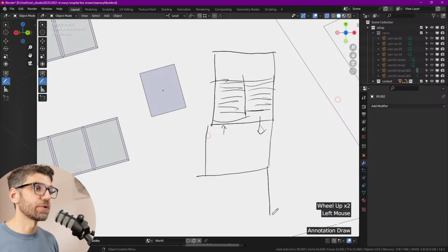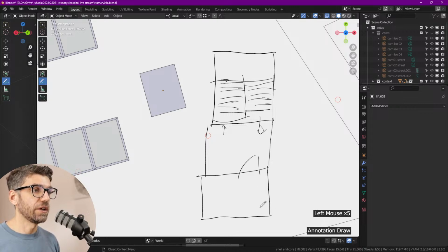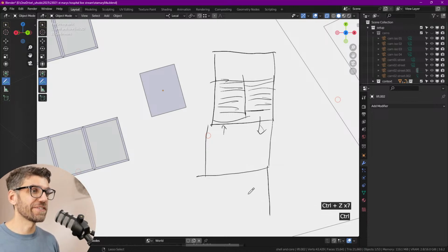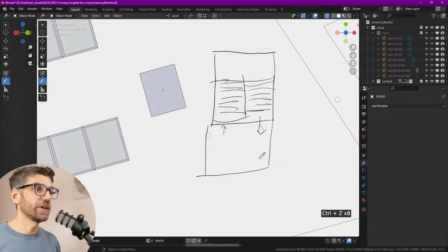In the US, they're a bit more stringent. You always needed to have a double lobby situation. In London, you don't always need that, and that has to go in the routes of the fire. Anyways, too specific. Let's keep it simple for now. We just have a simple one over here, and the door has to go in the way of the egress. These are silly things all architects have to know, right? So if this is in the upper levels, the door goes that way. This is in the outer levels, the door goes that way.